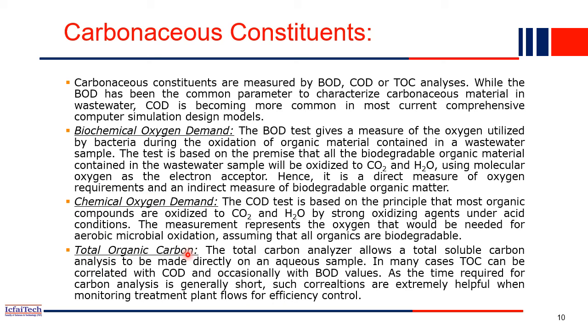Then lastly, the total organic carbon. Total organic carbon analysis allows the total soluble carbon analysis to be made directly on the aqueous sample. In many cases, TOC, meaning total organic carbon, can be correlated with the COD and occasionally with the BOD, right? If more organic carbon is present in the water, then more reactions will be taking place. That's why more oxygen demand will be there, right? So the total organic carbon also can give an estimation of how much the pollution level is in the wastewater. Depending on which quantity is more, we have to design the water treatment plant accordingly.